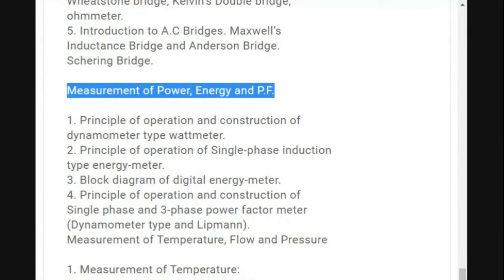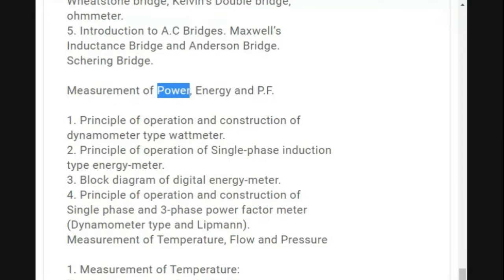Okay, so this particular power, if you talk about, it basically doesn't have the time component in it. But if you talk about the energy, energy is like power and time, both the components are there. So in the power we have only voltage and current and its multiplication, and as per its position in the power triangle diagram, you can have the cos factor or sine factor. Say for example, if you are talking about the active power, then the cos component is in multiplication, and the sine component in multiplication for your reactive power component.